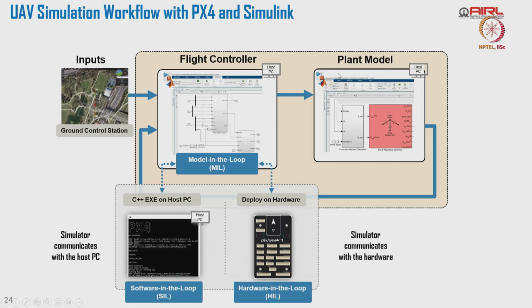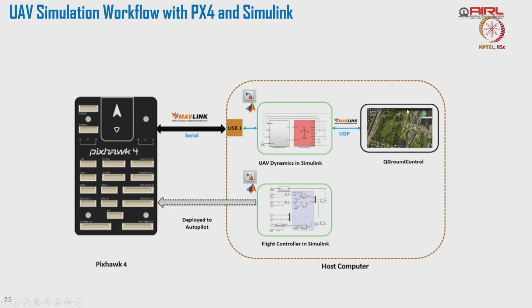One step further you can do, you can connect a radio control directly to PX4, and the radio control can give real time commands directly to PX4 in case you want to modify the predefined mission in the middle of the flight. You can try to simulate whether that communication is taking place or not. Those kinds of verifications are possible once you have this setup, right.